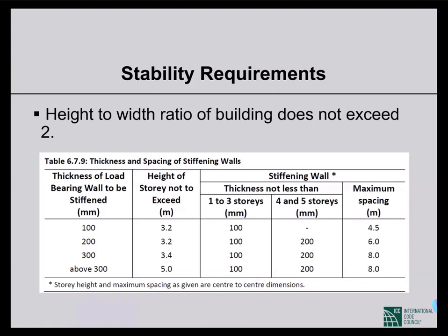But for cement grout, again, admixtures are not used, because for grout, strength is not a big concern, as grout is not considered to be load bearing in that sense. Grouts are used for bonding purposes. So with a high water cement ratio, we can have quite workable grouts.